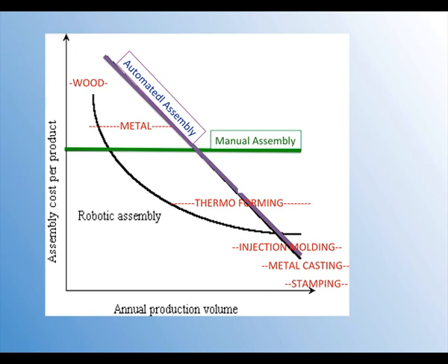Metal stampings, if we're talking about volumes greater than 100,000 units a year, can be processed in 10 seconds. Yes, investment cost is probably upwards of $1 million, but you're getting the lowest piece price with metal stampings. Injection moldings, you're really looking at parts that are somewhere between 10,000 and 100,000 parts. You've got tooling costs that are anywhere from $30,000 to $1 million, depending on the complexity of the part, but you're injection molding a part typically every 40 seconds. Again, it depends on the part.